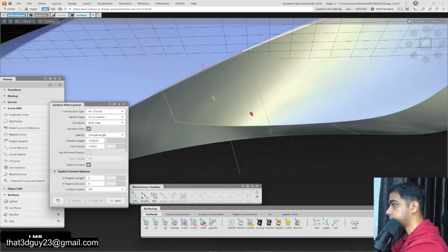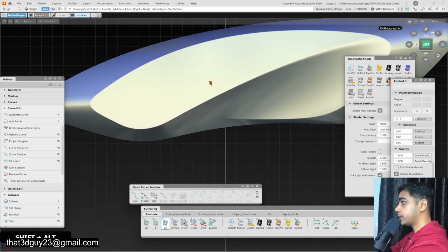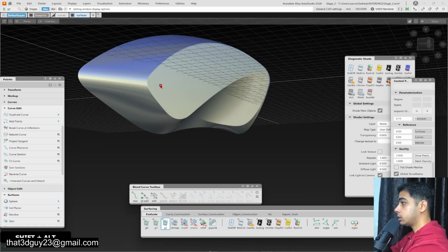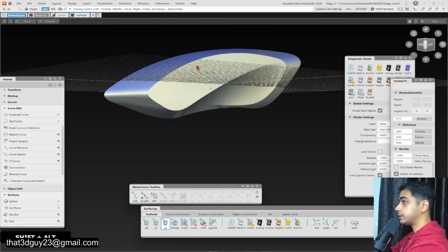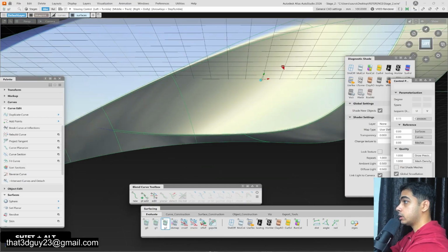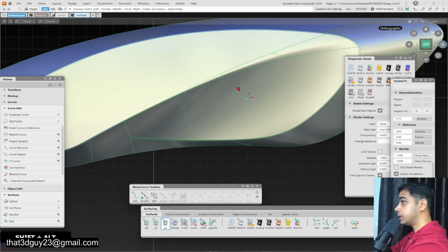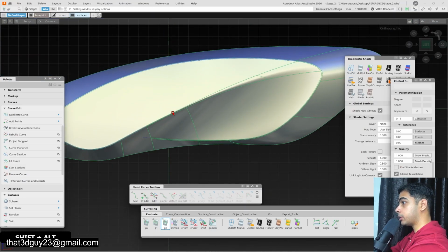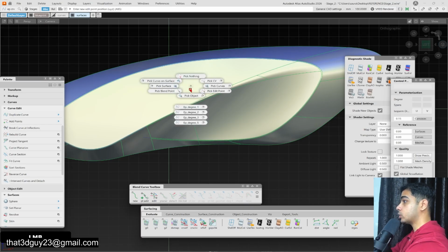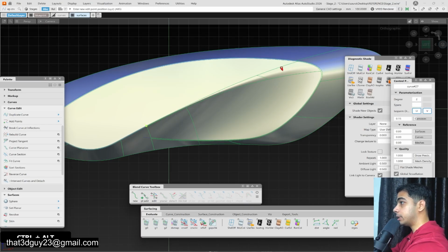And now what we are going to do is just use this entire thing and fillet it. So what I'm trying to do here is we are basically trying to retain the curvature of the paths, and if you see, we tried to manually build this curve here, right? Because what happens is when I was trying to extrude it all the way, it wasn't looking that good. So I wanted to maybe build a curve here all the way like this,